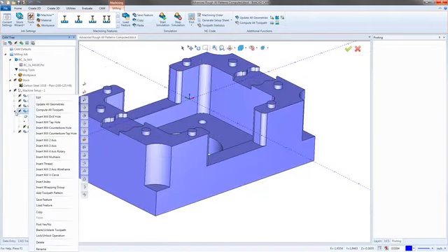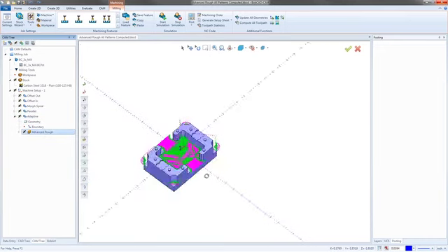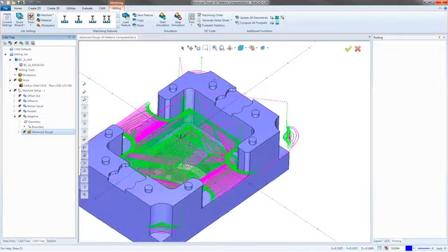And then the last one, I'll go ahead and move that up, is the adaptive function. So it looks like I went 1 inch deep. It goes 1 inch deep, then it starts its cut. Now the big thing with this is I'm all right with it taking a very aggressive, heavy depth of cut like that. What I'm not okay with would be if I left my normal 50% step over. It's just way too aggressive on the tool, and I'd rather have this tool come in and just shave it, but I'll be moving real fast, and I'll be at a much lower depth.